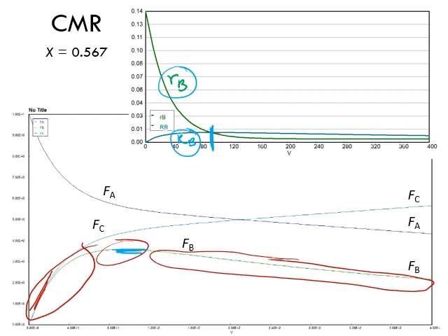However, after this, we'll see that the rate of formation of B decreases, right? Capital RB, the rate of diffusion, almost remains constant, because the concentration of B almost remains constant, but the rate of formation of B decreases. That's because the concentration of A has decreased, and also of course the concentration of C has increased, and because it's a reversible reaction, the decrease in concentration of A and the increase in concentration of C actually reduce the rate of reaction. Therefore, the rate of reaction drops below the rate of diffusion of B. So B is diffusing at a rate faster than the rate at which it is formed. Therefore, its molar flow rate will decrease, and we will get a conversion of 56.7%.